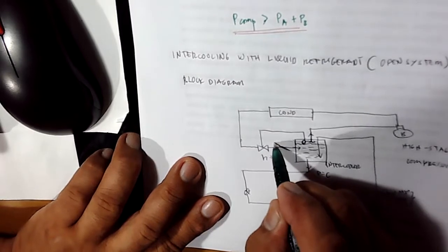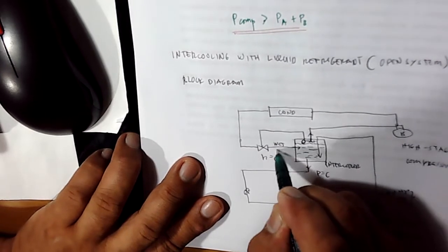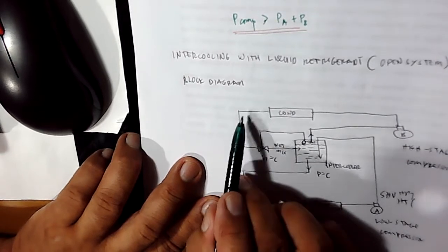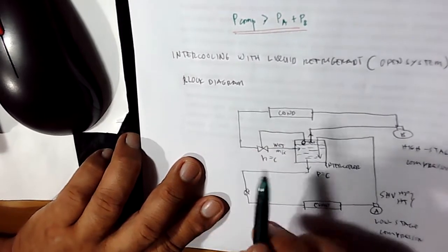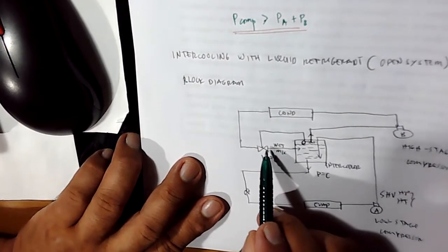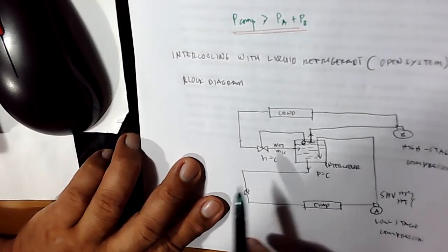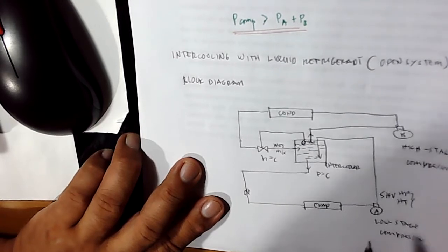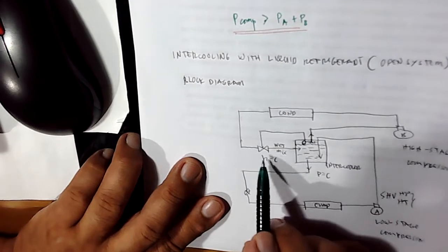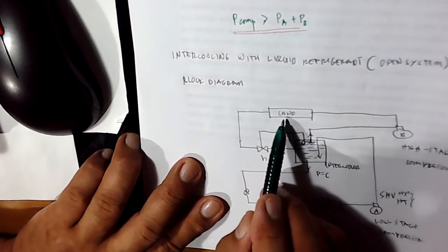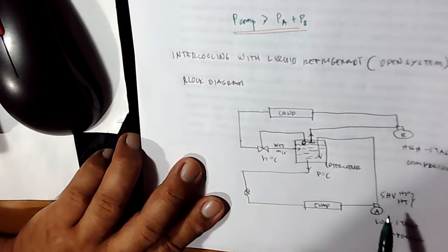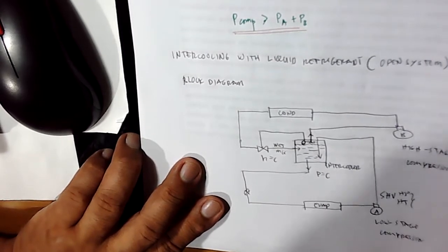This is considered wet, coming from the high side, your condenser side. But then after this is a valve. It will of course reduce the pressure so that the pressure coming from the low stage compressor meets with the pressure coming from the condenser, reduced again to the pressure coming from the low stage.